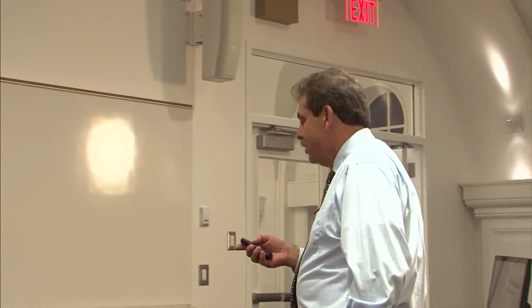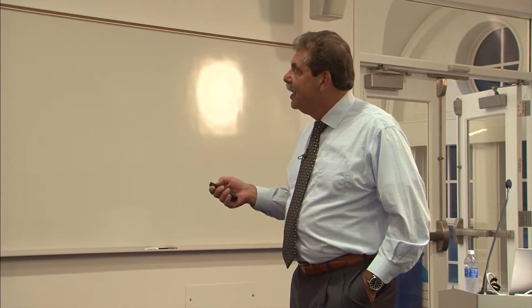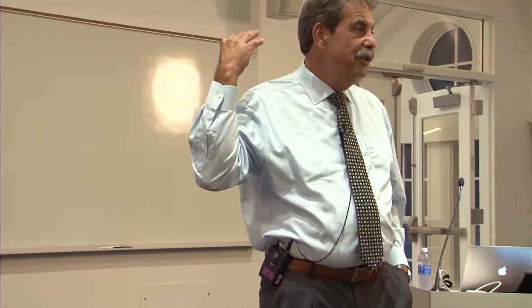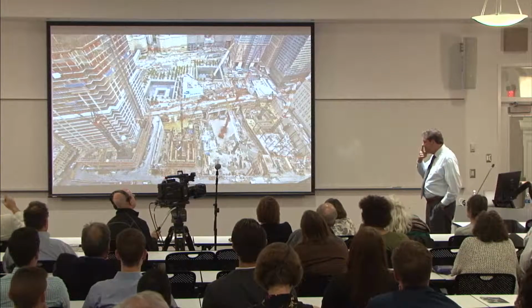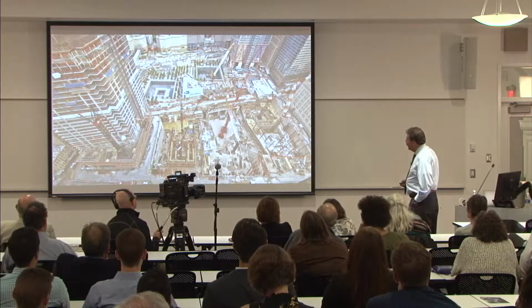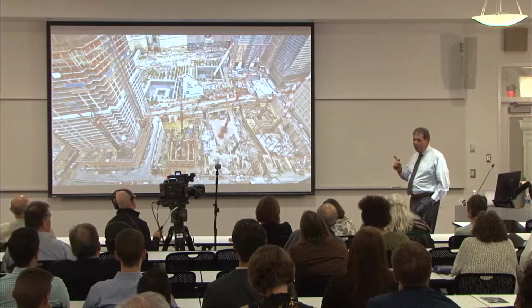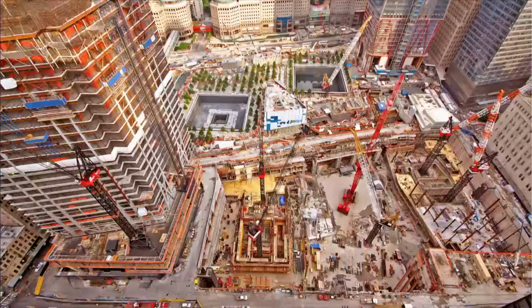And part of that was we had to actually remove a temporary station, build a new temporary station, and then demolish the old foundations of the H&M building that I showed you in one of those very early slides. So logistics was a major issue on this site. We literally only had one lifeline, and that was the roadway atop the one line. The one line, which is sitting on that underpinning, was the lifeline. That is where 90% of the materials came into the job in the first 4 years of the project. Not only for us, but for the memorial and for the towers. That's where everything came in and everything went out.